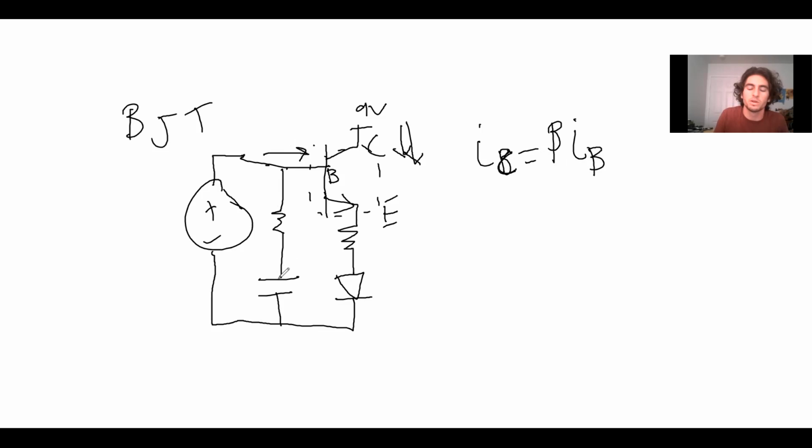So in our case, since our capacitor is really small, if we discharge a lot of current, it's going to discharge in like 0.001 seconds. It's going to be super fast. We want to discharge a very small amount of current, and that can just be amplified by this BJT. Finding the time constant for this is not really trivial. It has to do with the input resistance of this BJT. So I'm not going to, maybe I'll post the notes after.